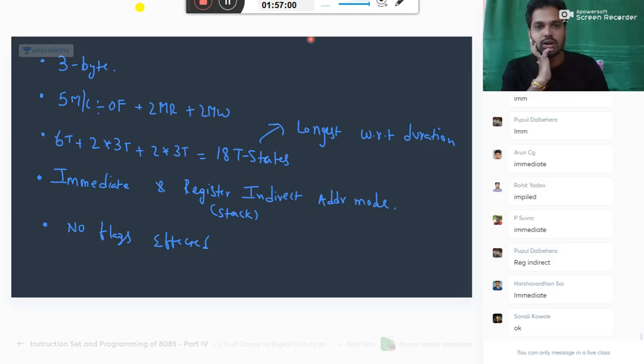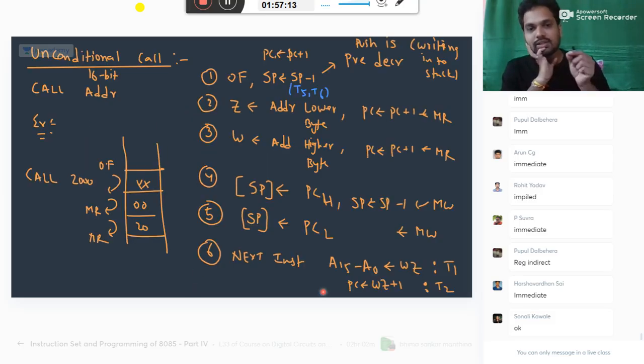So that is about your call instruction. Here, whenever 6 T states comes, I always give you the reason for 6. Remember that. Whenever 6 comes, I will tell you why 6. That extra 2 T states are required for what reason, this you should remember.